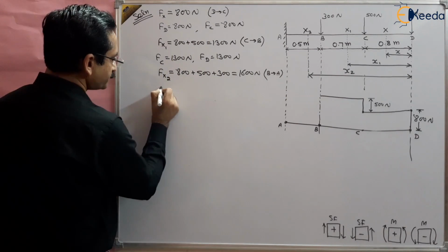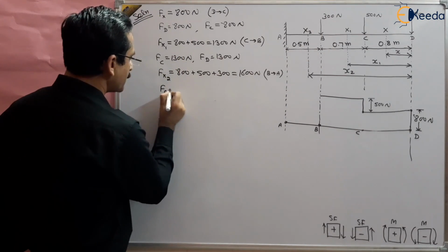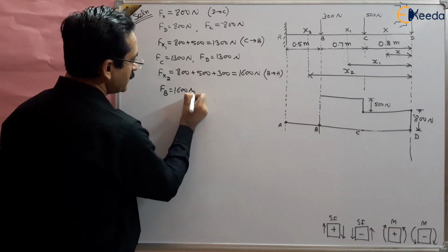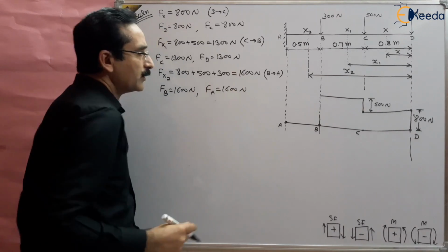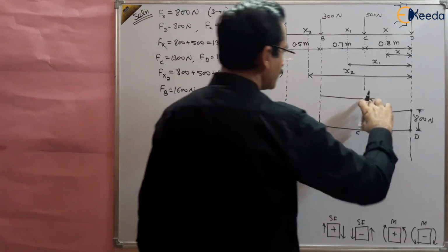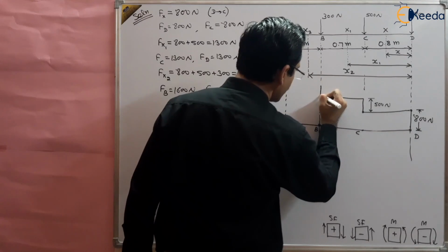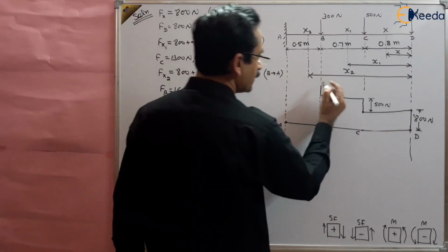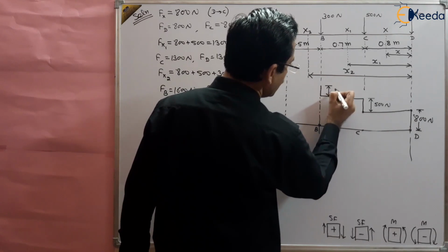So you can take the extreme points. At B, what is the force? At B, it is this force 1600, it is constant, and FA is also 1600, right? So we have already made 1300 load, 300 should be added, so add 300 here. So at B point, this is 1600. We have added the 300 Newton of load here, right?